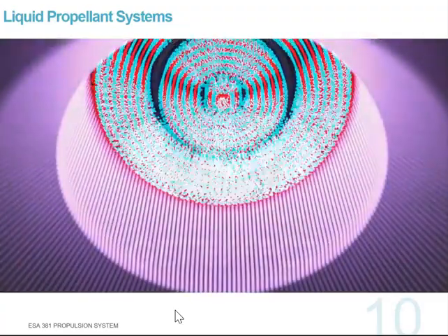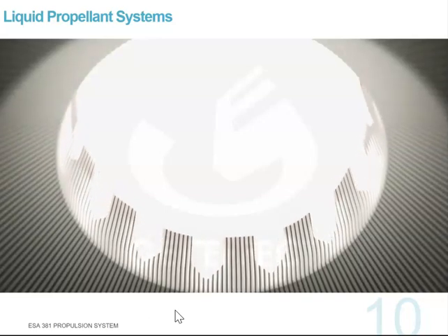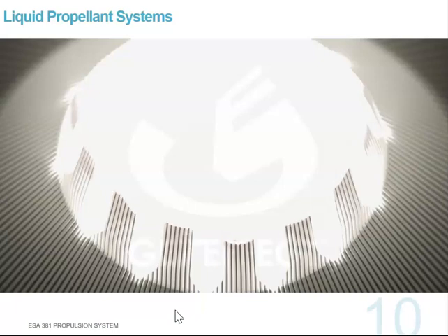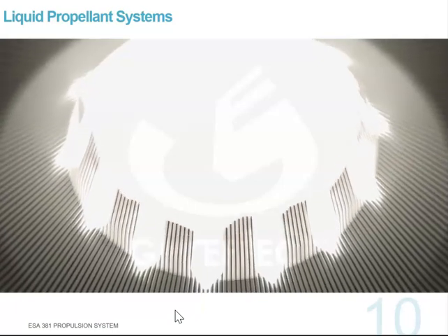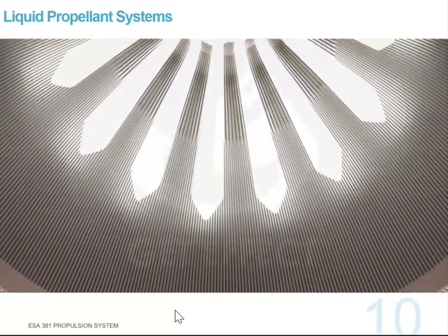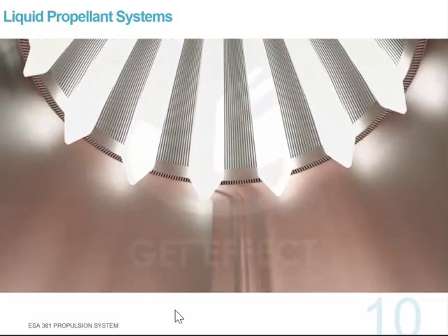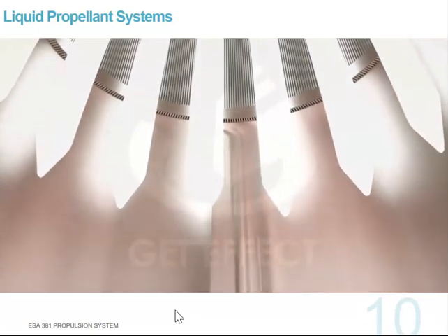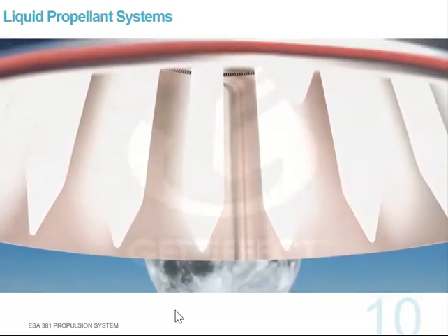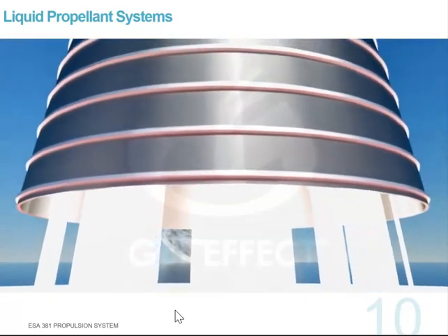This bipropellant mixture was subsequently burned, producing extremely hot and high-pressure gases, continuously accelerating as they progressed through the converging section of the nozzle, until they reached the throat, where they achieved the speed of sound. Subsequently they entered the divergent section of the nozzle, and because the flow is now supersonic, they accelerated as the area increased. They then entered the thrust chamber extension, an attached component that improved the thrust chamber expansion ratio, and finally were expelled at high speed to the atmosphere, providing thrust.